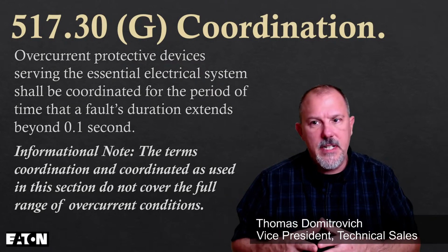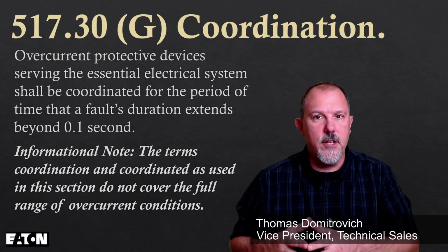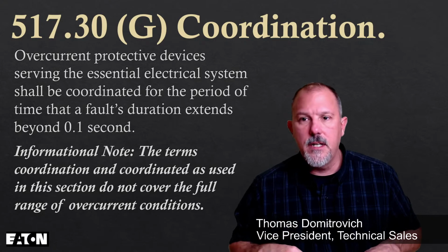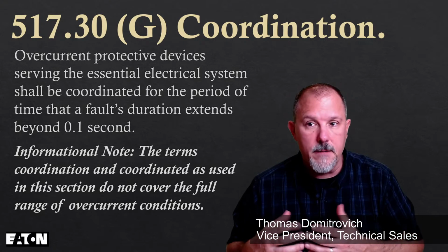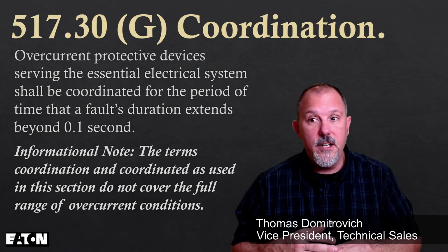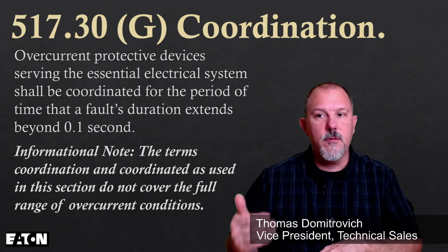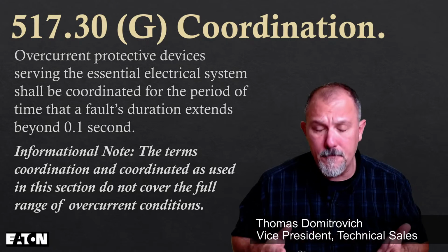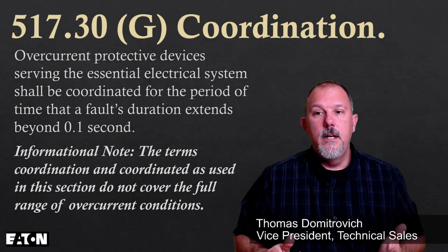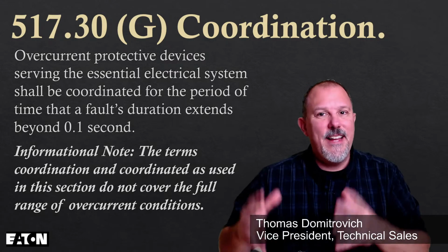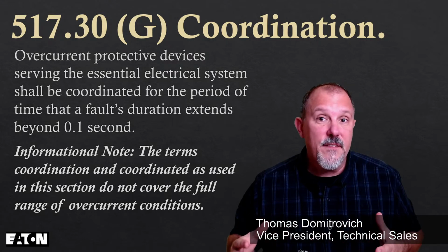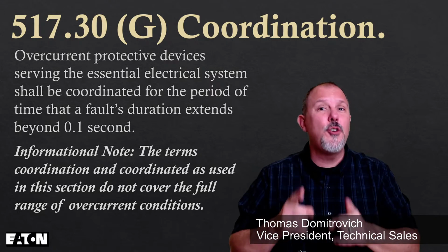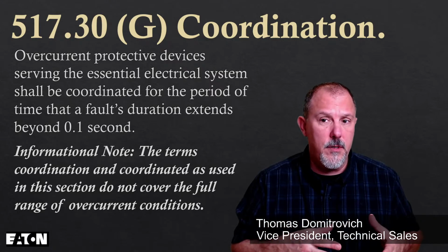If we look at 517.30(G) out of the 2020 National Electrical Code, it says overcurrent protective devices serving the essential electrical system shall be coordinated for the period of time that a fault's duration extends beyond 0.1 seconds. Now, that's not a definition, and there really is no definition for coordination in the National Electrical Code. I'm going to show you a NEMA definition pretty soon.